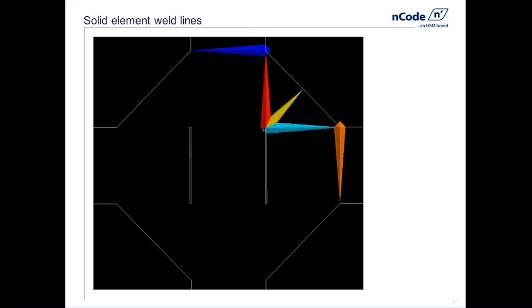Because these welds are not attached to actual nodes or elements, we needed some sort of mechanism to display the weld location as well as the results. And so these markers start out, the fat end actually is a location where the weld initiates, and then they are basically pointing in the direction of the stress linearization line, and their length represents the length of the line that was calculated. And here you see we have both the toes as well as the throat calculation showing here, and in this case actually the one throat calculation is the one that drives the fatigue result.